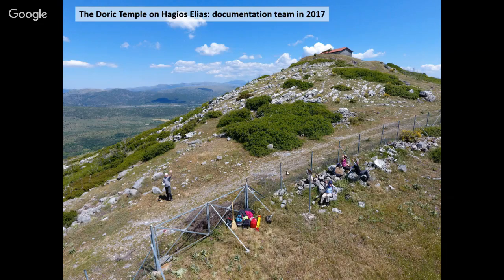I'd say you make sure that you have the time. So never do what I've had to do in several cases, that you run the last set of photogrammetry shots and then you don't process them, because then you always come up with surprises the following day that you're missing something. If you do good planning and basically overshoot, so do too many rather than too little, you can always chuck out the ones that are not needed.